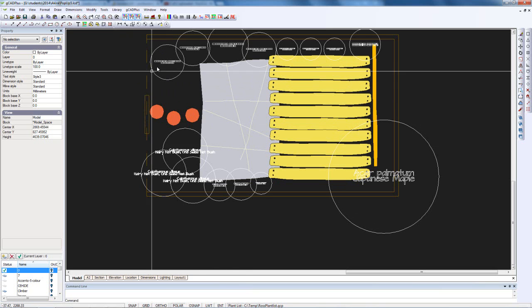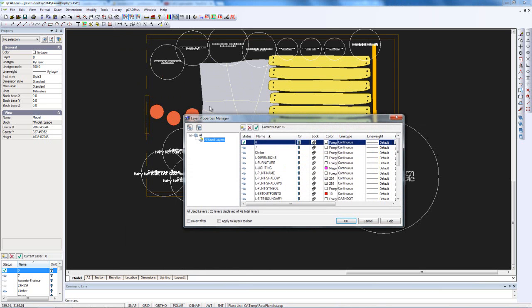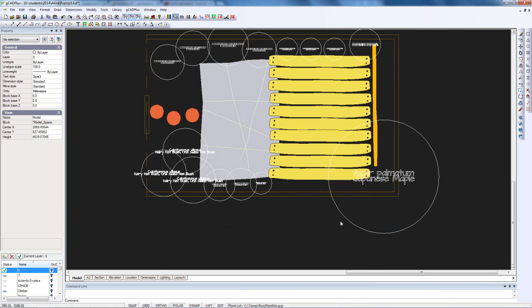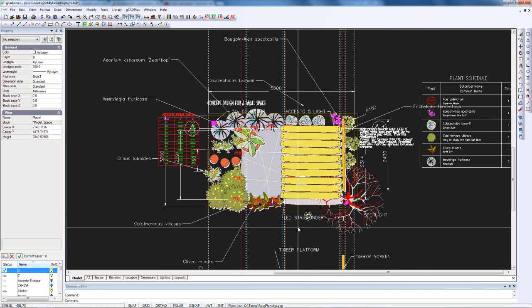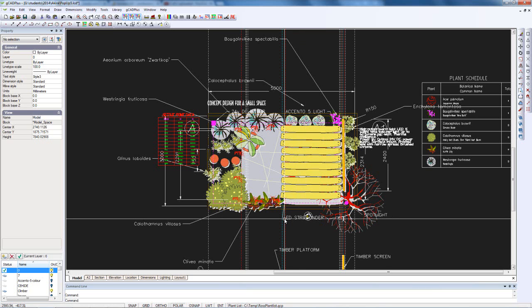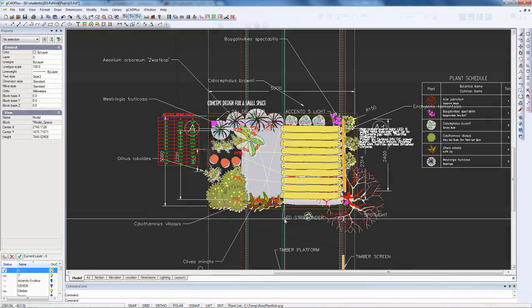That's now happened. At this stage, I'd go back to my layers. I'd right click and I'd say turn the visibility of all layers on, and then I'd come to my SketchUp layer and text layers, and just turn those off. So we're now back to our design, and we can turn our layer groups on and off at will. So we're now in a position to move to the SketchUp environment and to take that base information and build a 3D model.